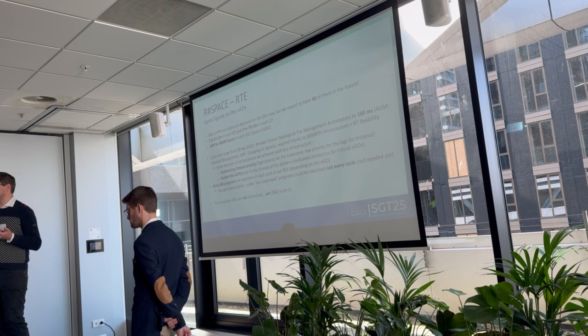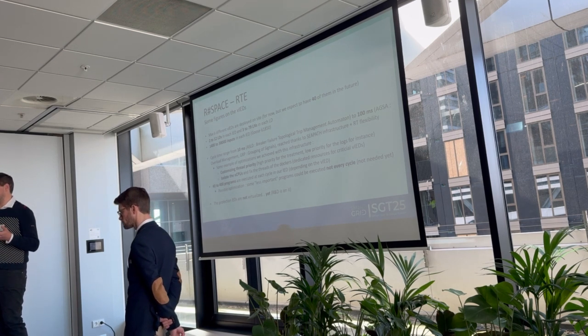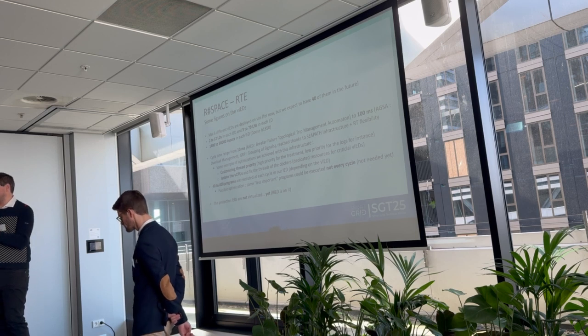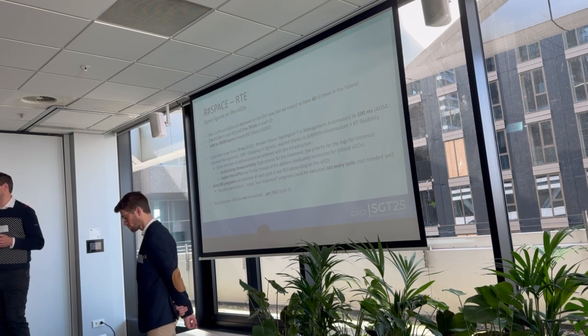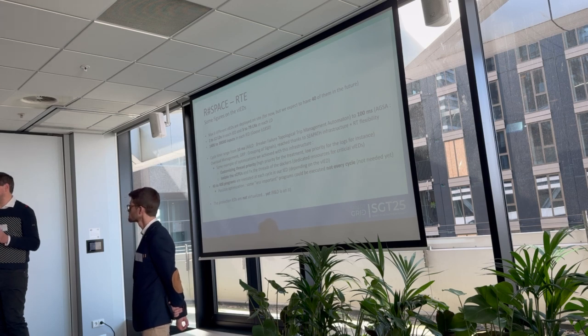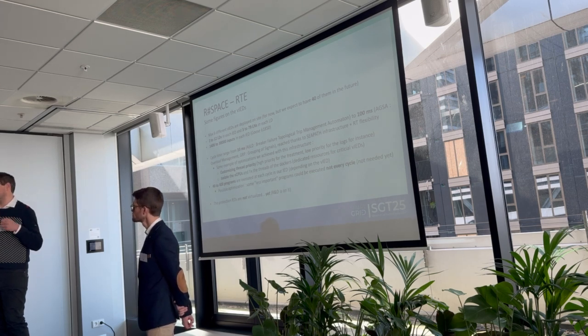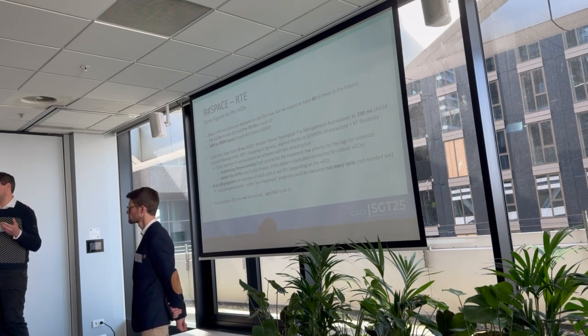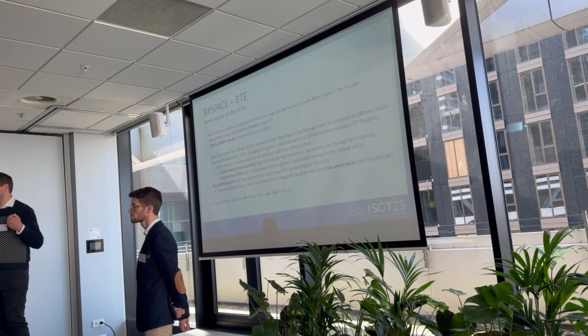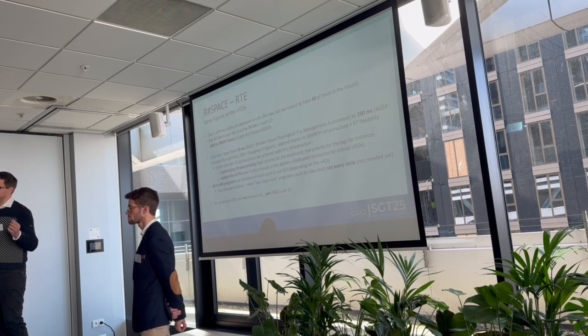So we already performed some tests isolating certain Dockers on certain vCPUs. The idea is, for instance, for the circuit breaker failure management automaton, we could not afford to be over 10 milliseconds of cycle. It's critical for us, of course. And in this case, this one has its dedicated virtual CPUs.